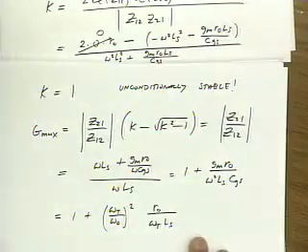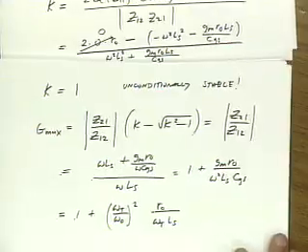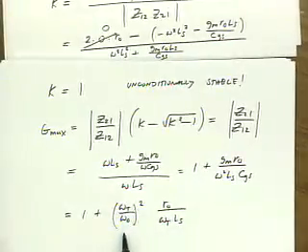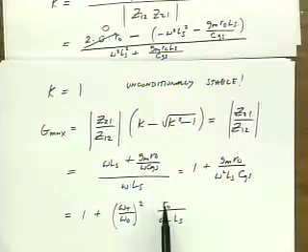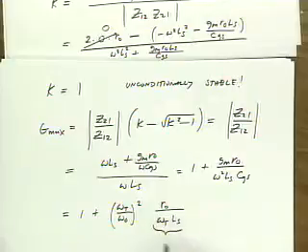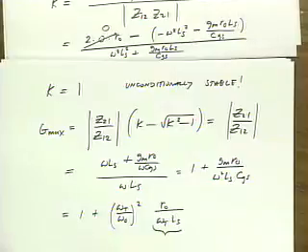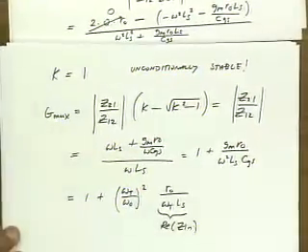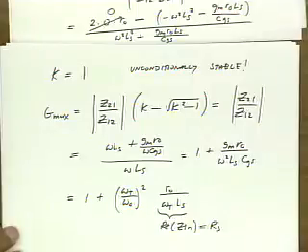It's basically a ratio of the omega T of the device and the operating frequency, and a ratio between Ro and a resistance equal to omega T Ls. Now remember omega T Ls, because it's going to be important. What we're going to show is this is actually equal to the real part of Zin. Okay? And we know that we get maximum gain when we impedance match, and so this is actually going to equal Rs, the source resistance. Okay? Any questions about this calculation?